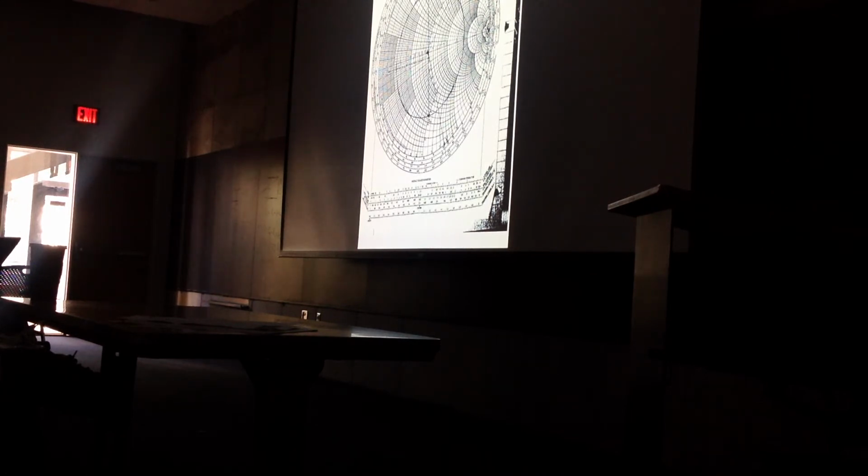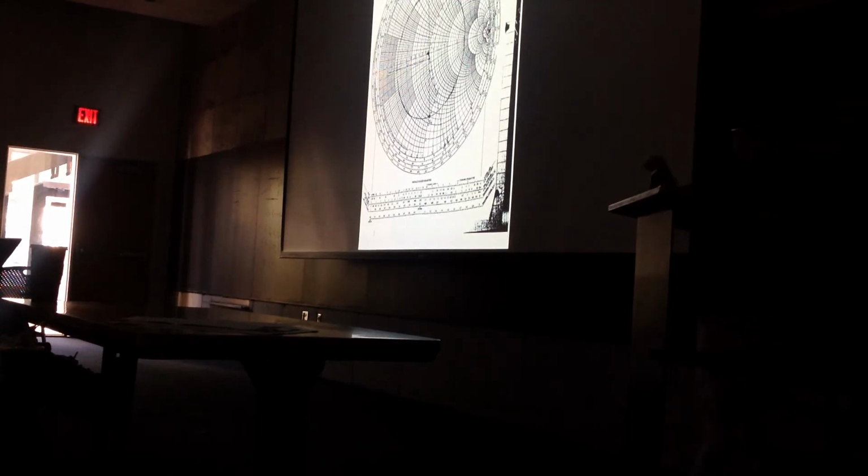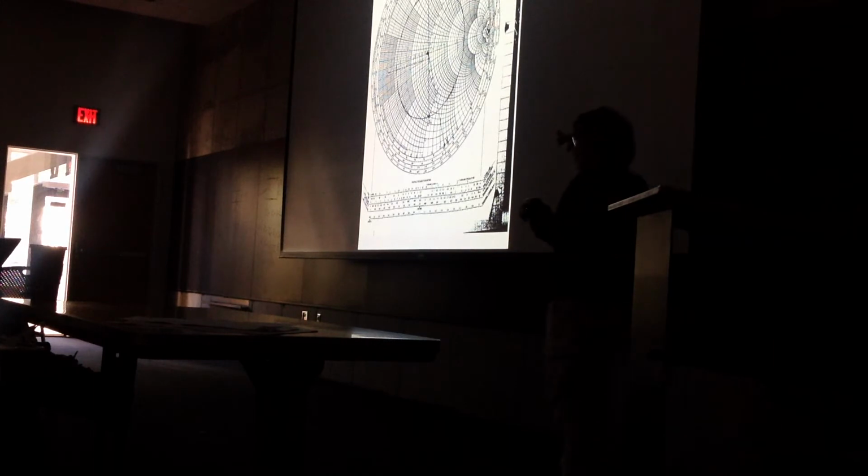So originally you are at 0.115 lambda, and you get to 0.178. So you take 0.178 minus 0.115. That's how much wavelength you need to go to find a matching location.